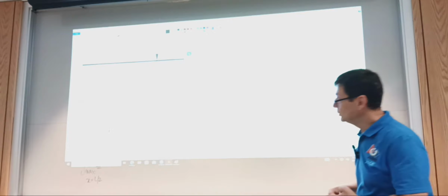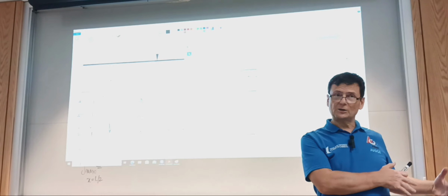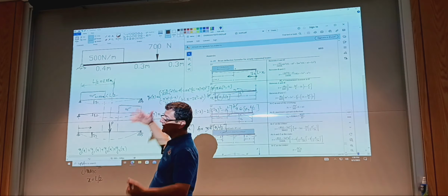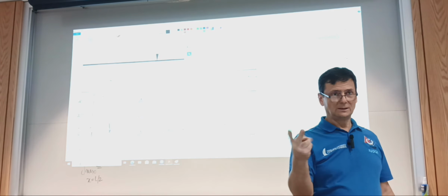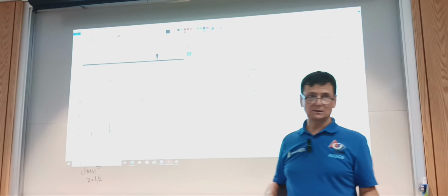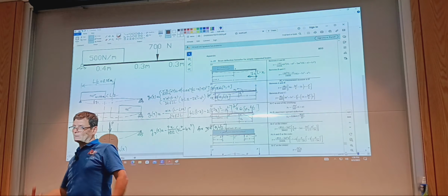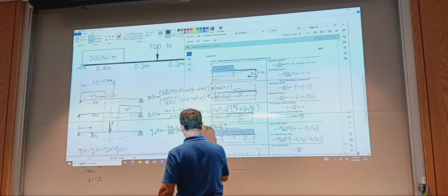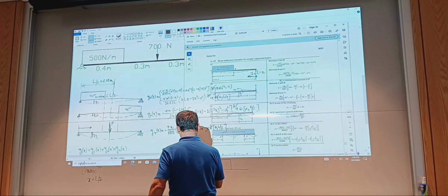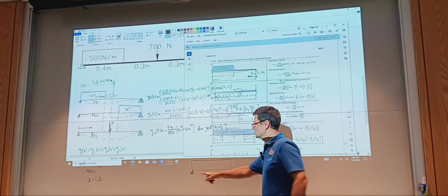Okay? Do you understand how the principle of superposition works? So whatever is documented in the appendix, see if you can combine them to get your loading case, possibly with mirroring, and of course with reversing, so we can have, for example, cases where the distributed load has to act from below. So if I have a case like this one, a simply supported beam with a distributed load, do you understand the difference between these two?